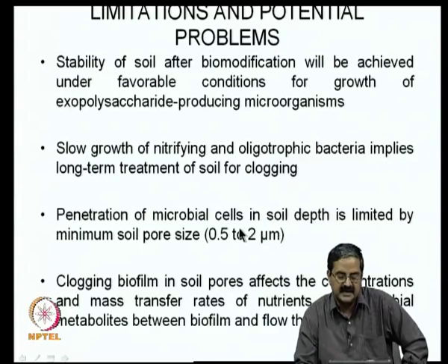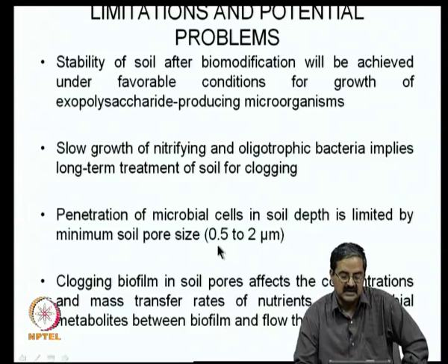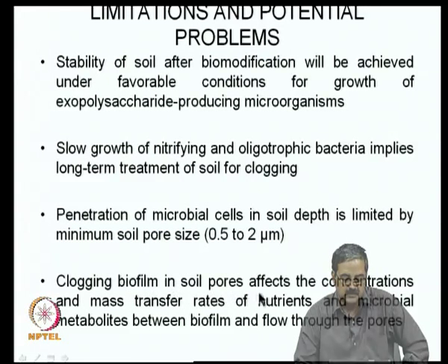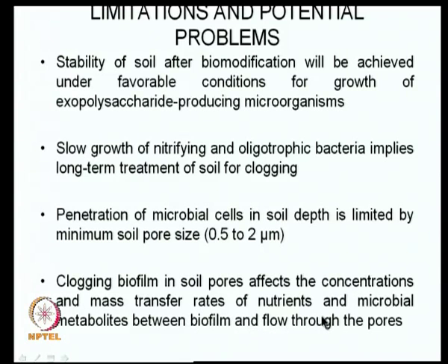Penetration of microbial cells in soil depth is limited by minimum soil pore size. As I just mentioned, the size of the pores is quite important, and fortunately I think you have bacteria for every soil size. Clogging biofilm in soil pores affects the concentrations and mass transfer rates of nutrients and microbial metabolites between the biofilm and flow through pores. So, this is an important point to be noted.